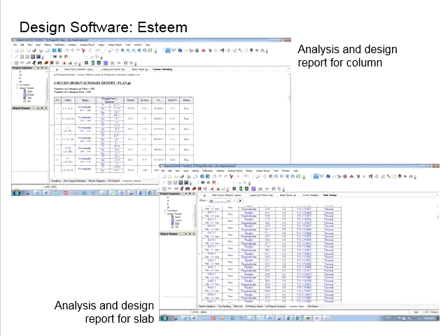And then in terms of the design output, not only for you to check the design, there are many ways for you to cross-check the inputs that you use in the design, because there are calculation steps outlined and demonstrated by the software, as well as you can make some logical comparison between structural elements. Then you will know more or less whether your model result is reliable and accurate.